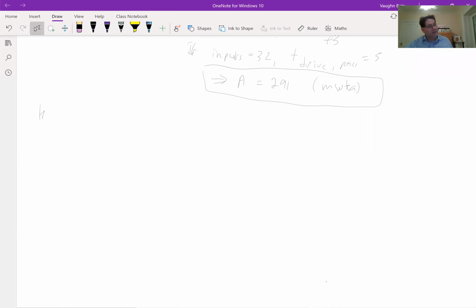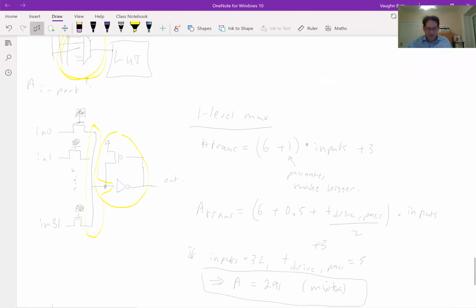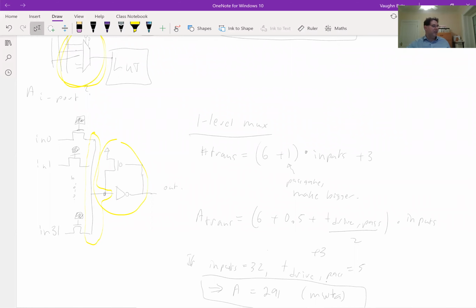Bunch of logic gates connected. Yeah, okay, so I could give up on pass transistors completely, and I could just build this as AND and OR gates, but it turns out that's actually a lot bigger still. So pass transistor logic will save us area over switching back to basic logic gates.